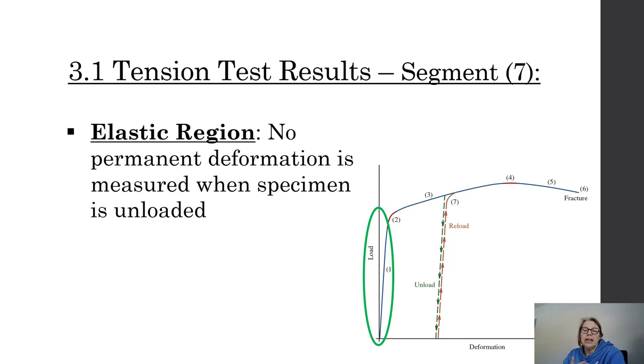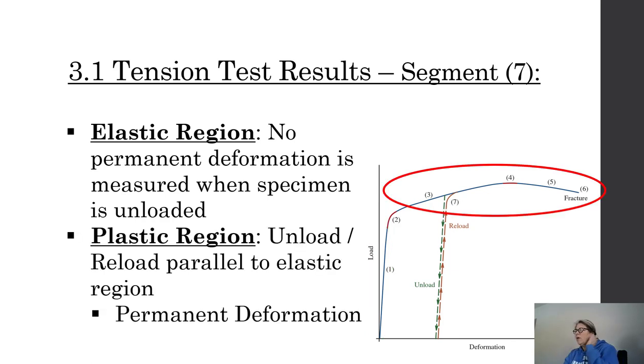So you're going to have to start making sure that you always check: am I within the elastic limits of my material, or have I gone over, where you have permanent deformation? In the plastic region, you have permanent deformation, you have permanent strain. You will never go back to the original length. When you unload, it will be slightly longer than what you started. It's not going to go back. It's plastic deformation. Okay, it has permanent strain built in.